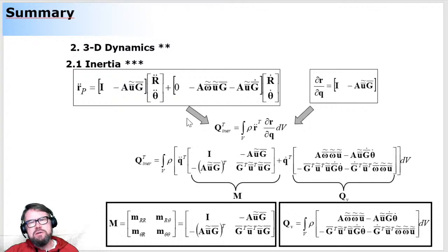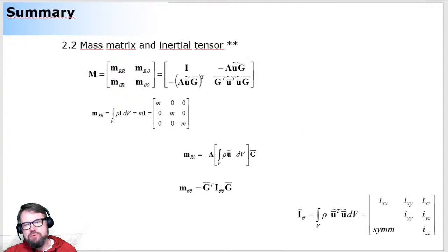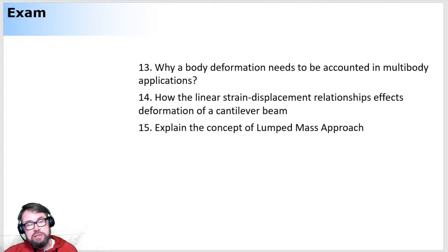You need to go all the way back to how generalized inertial forces are defined. In generalized inertial forces, you will have this explanation of acceleration, and this is where you have the G. So it's a very lengthy, complicated explanation. Finally, when you do all that, you see that the relation is obtained with the help of G. This is going to be your inertia tensor, and you can map that to any rotational parameters you want. Again, how you make it happen is with the help of the G matrix. Lengthy explanation. This is the equation of motion, for which there is no question.